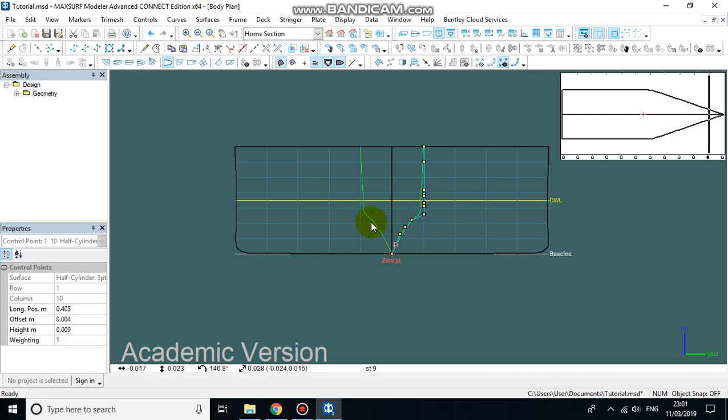So you might want, like here, I've put a concave bow in here. You may want to move all of these, so I just used a left click and hold to select all of the points, and now if I hold shift and move them, they'll only move in one plane, as we found before.